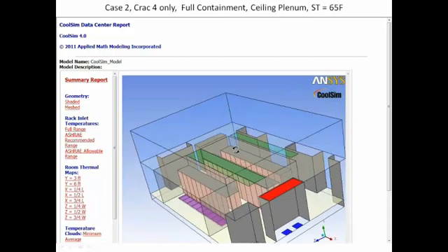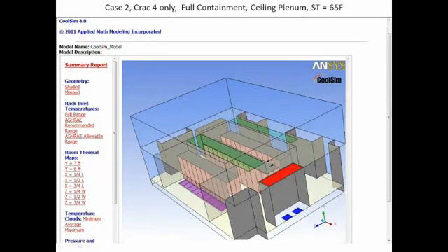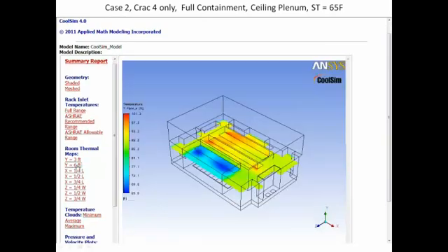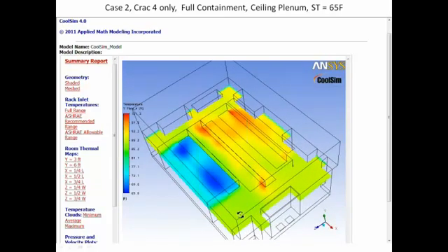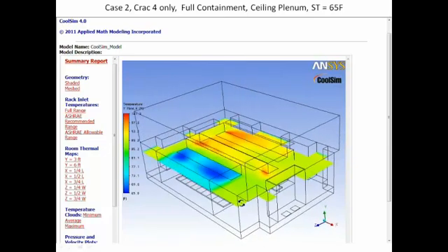Only problem with this method, I tend to prefer hot aisle containment, and I'll show you here why. If you slice this thing at 6 feet, it gets pretty warm in that room. Yeah. Makes people uncomfortable even though it works. That's right. If you do cold aisle containment, which is what I did here, the servers are happy, but the humans are not.